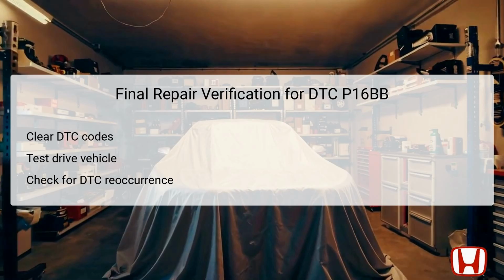During the drive, various electrical loads can be engaged to assess whether the alternator now functions adequately to maintain voltage levels. After completing the test drive, it is important to recheck for any reoccurrence of the DTC. This final step confirms that the resolution of the problem has been effective and assures that the vehicle operates reliably.